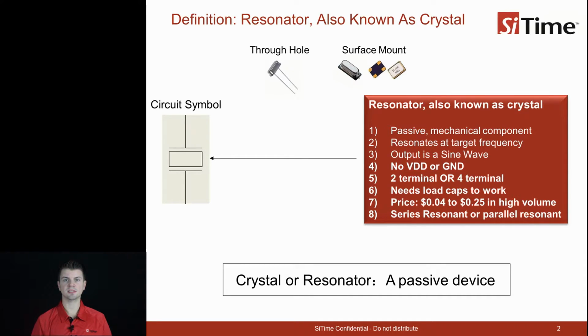The construction of series and parallel resonant crystals is identical. They only differ in the way the frequency at 25 degrees Celsius is calibrated. While crystals are intrinsically simple circuit elements, their parameters, such as equivalent series resistance and maximum drive level, must be closely matched to the particular oscillator circuit in the IC. This is to guarantee startup and proper operation under all conditions.